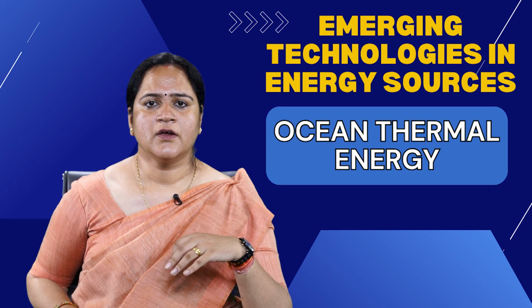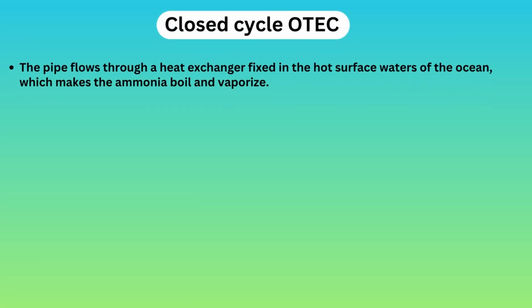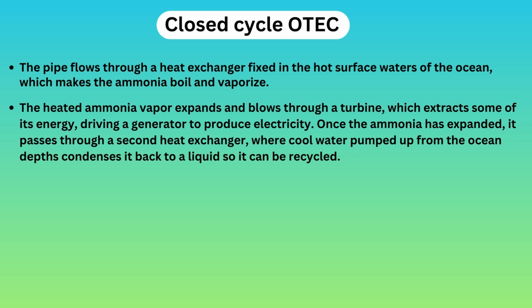Now the closed cycle ocean thermal energy system. In this, the pipe flows through a heat exchanger fixed in the hot surface waters of the ocean, which makes the ammonia boil and vaporize. The heated ammonia vapor expands and blows through a turbine, which extracts some of its energy, driving a generator to produce electricity. Once the ammonia has expanded, it passes through a second heat exchanger where cool water pumped up from the ocean depths condenses it back to a liquid so it can be recycled.